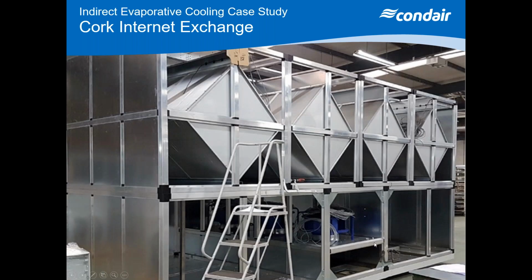So this is what the system looked like. And just for scale, here's a pair of step ladders that you can see in the photograph, just to give you an idea of how big these units are. And air is drawn up from the hot aisle, from this section here, going up through the fan. It's split, goes left and right, over the first heat exchanger, over the second heat exchanger, and then goes back down into the cold aisle and then circulates back round. And on the cooling side, air comes in through the evaporative humidifier, over the first heat exchanger and over the second heat exchanger, and then circulates round or is exhausted, and we're constantly going around like that.